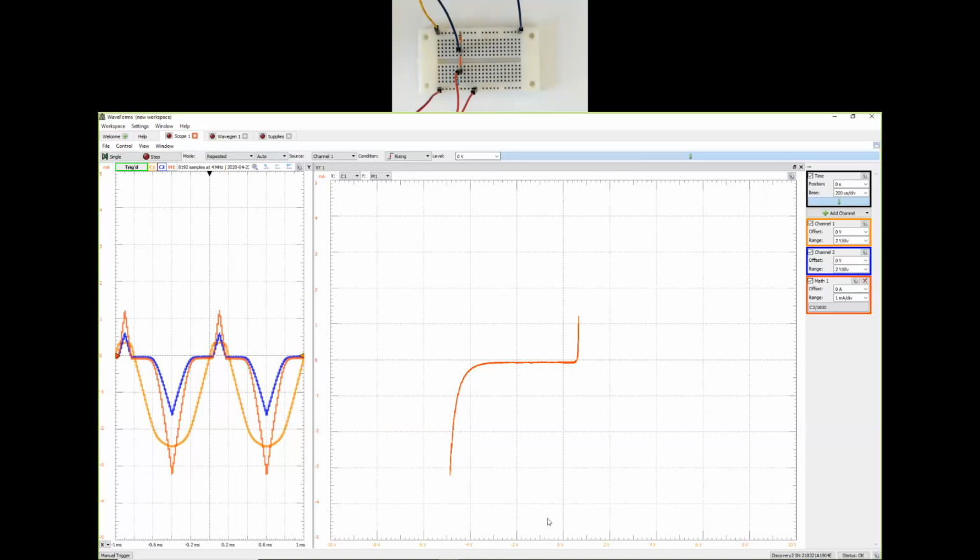And I hope you are able to see here that it is functioning exactly the same way as the 1N4148 diode. In the forward biased region, it rises exponentially around that 0.7 mark, but on the negative side, around -5 is where it breaks down. So much earlier, in the previous experiment, we were not able to explore this breakdown region, which we are able to do now. So the data looks good, which means that I'm ready to export it to Matlab and sketch it over there.